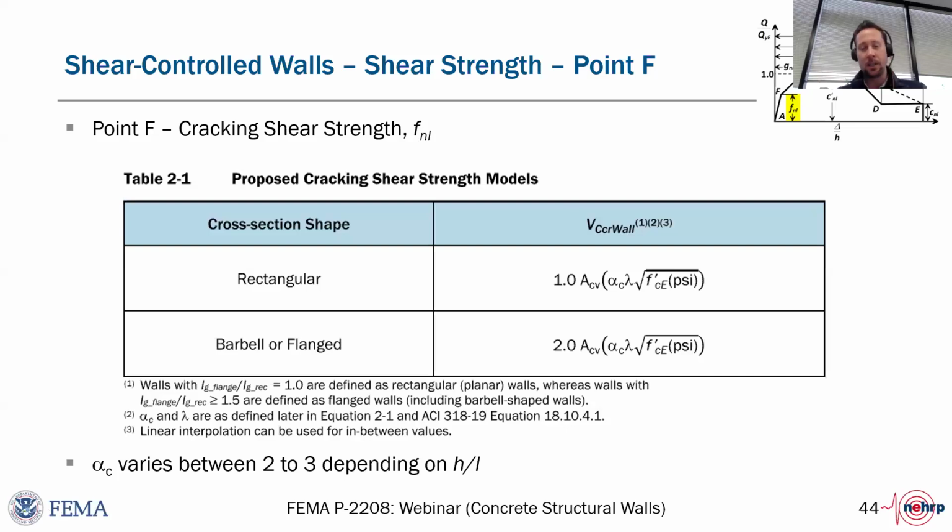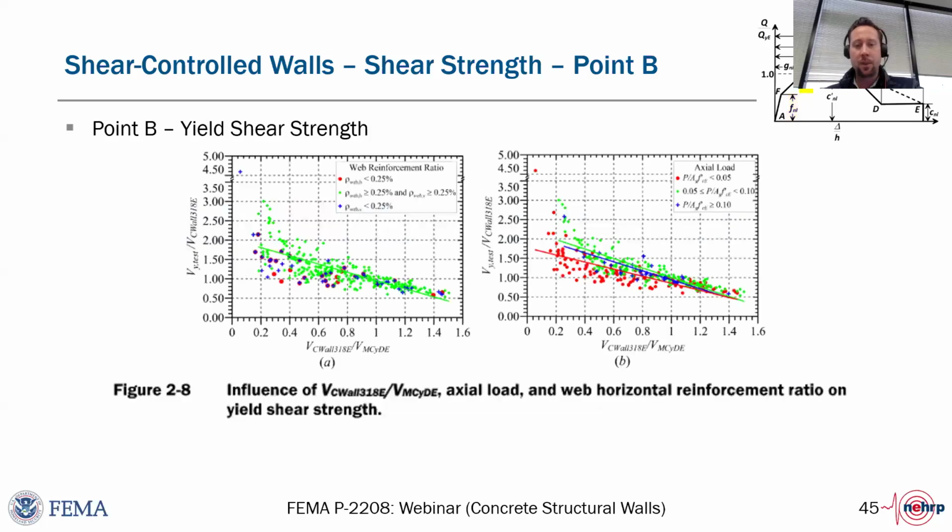It cracks later, essentially. And I think the main thing there is you're seeing that as you're going toward the flange, particularly, you have more of a nodal reaction, if you think of a strut and tie type concept, that allows for crushing to occur later, and I guess diagonal cracking to occur later. Really, not the crushing, yes, but also the diagonal cracking.